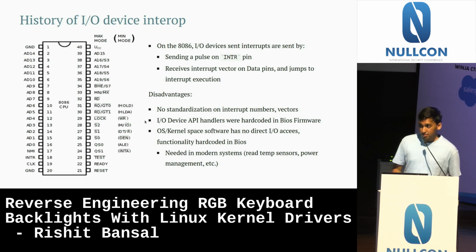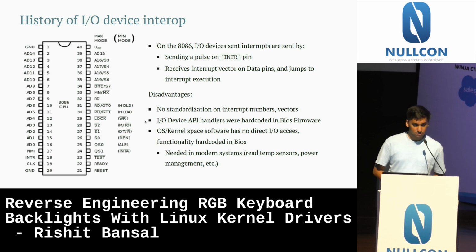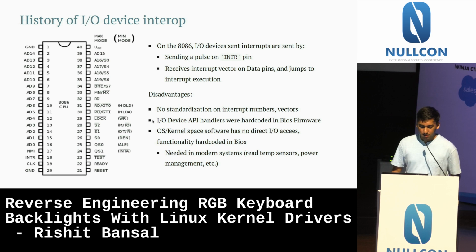The disadvantage of this approach, at least now, maybe not at that point in time, was that there was no standard to maintain these interrupt numbers for each I/O platform. When the 8086 was made, there were very few operating system standards emerging. The people making the chip were the same people writing the software for the chip in many cases.